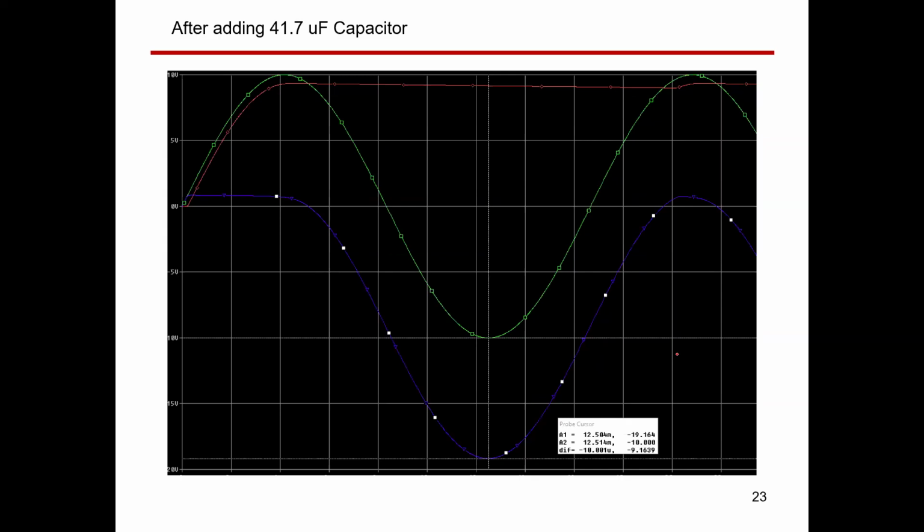Let's take it step by step now. So firstly, unfortunately, the waveforms are not labeled here in this screenshot, but we can recognize the waveforms from our understanding. So this here, guys, represents the capacitor volt or V out. So this is V out or V across capacitor. As you can see, you have a difference from the peak value of the supply volt. So Vs is the green one. So this difference is nothing but the turn on volt of your diode.